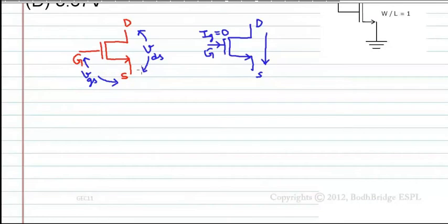Now, first of all, when will current exist, that we should know. There are some conditions in MOSFET. First of all, VGS is a very important voltage. When VGS is less than some threshold voltage Vt, otherwise there exists no current. Whatever be the voltages, whatever be VDS, there will exist no current at all. This is called cutoff region.